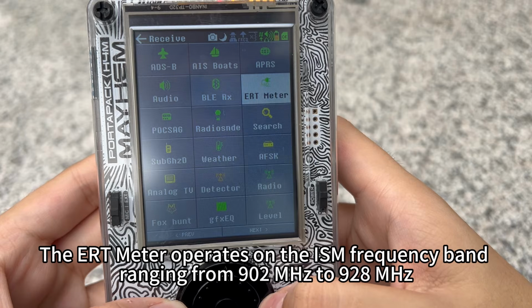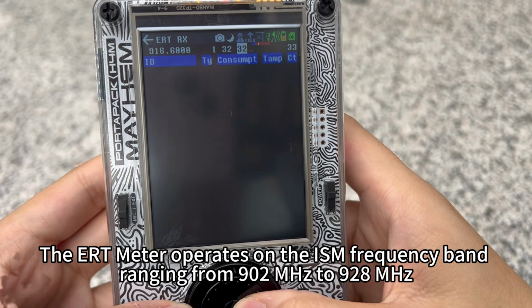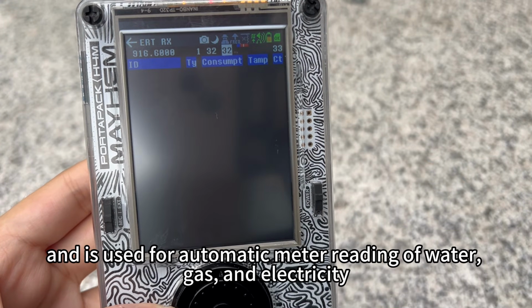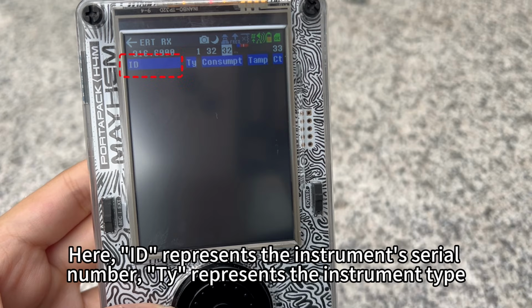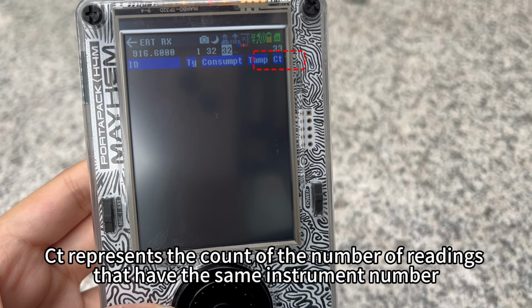ERT Meter. The ERT meter operates on the ISM frequency band, ranging from 902 MHz to 928 MHz, and is used for automatic meter reading of water, gas, and electricity. It supports protocols such as IDM, SCM, and SCM+. Here, ID represents the instrument serial number, TI represents the instrument type, Consumption indicates the meter reading value, and TAMP represents the tamper-proof label. CT represents the count of the number of readings that have the same instrument number.